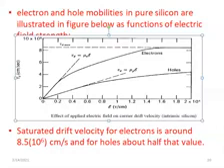Now, if you look at this carefully, you see that the velocity for the electron, given by this first curve, becomes constant at this point, and if you trace it, it will give you around 8.5 times 10 raised to the power 6 centimeters per second as the velocity.